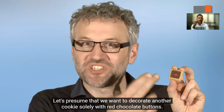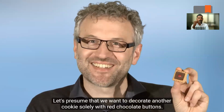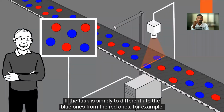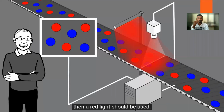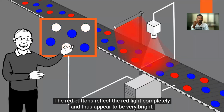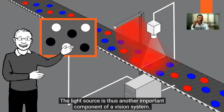Let's presume we want to decorate another cookie solely with red chocolate buttons. If the task is simply to differentiate the blue ones from the red ones, for example, then a red light should be used. The red buttons reflect the red light completely and thus appear to be very bright, while the blue ones primarily absorb the light and appear as dark. The light source is thus another important component of a vision system.